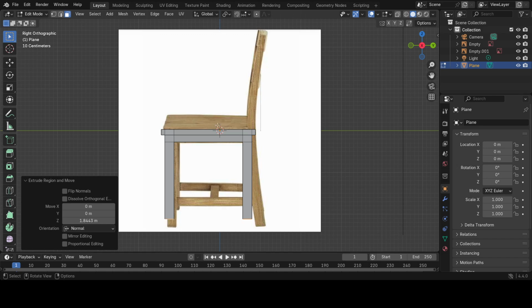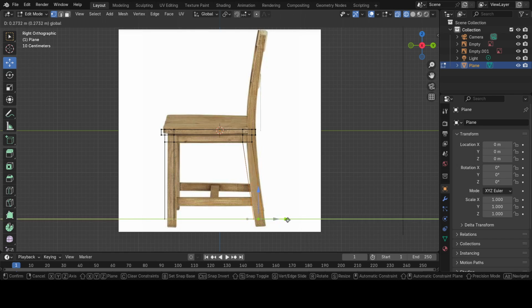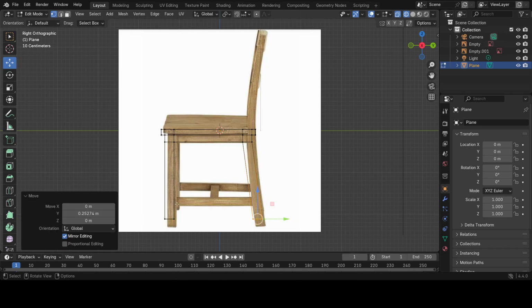All right. So next, we're going to go to the and bring this, you see we have a bit of a tilt right here as well. So what I'm going to do is hit 1 and then Z for the wireframe, so I get all of these vertices that I want. And then again, move these back about like this. So I'm fine as far as like the difference between the image and this. This is just a general guide that I'm using this for.